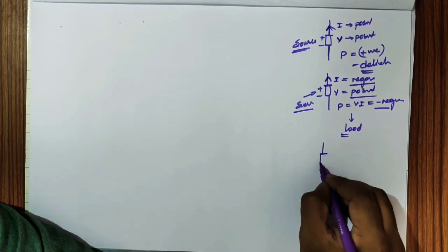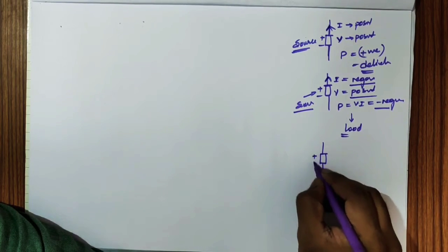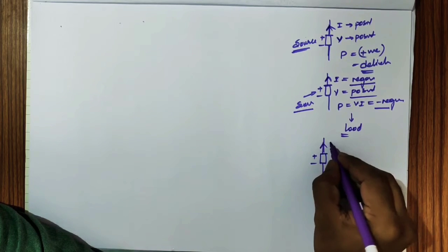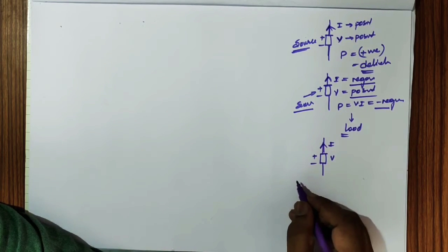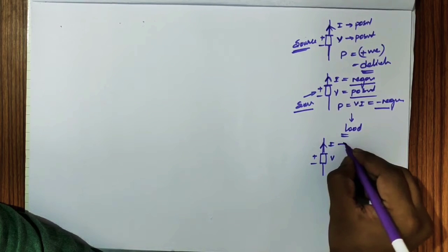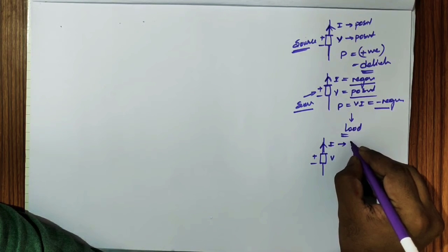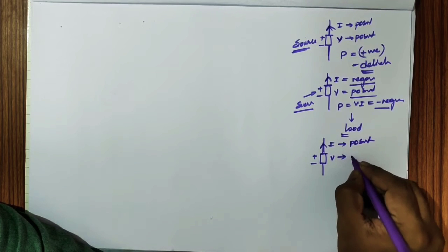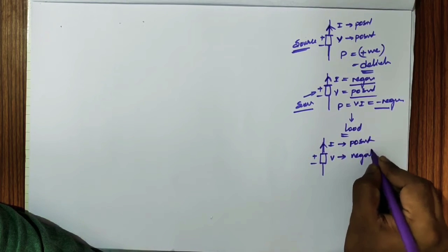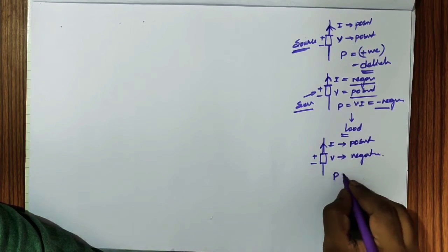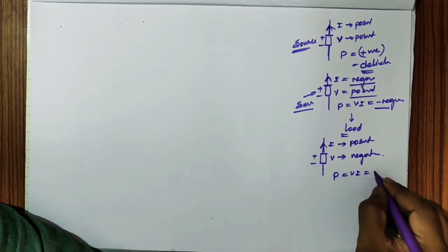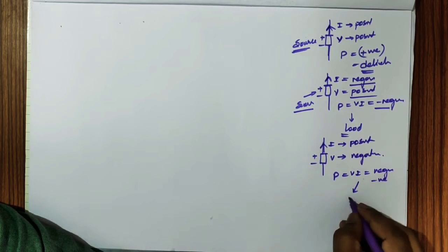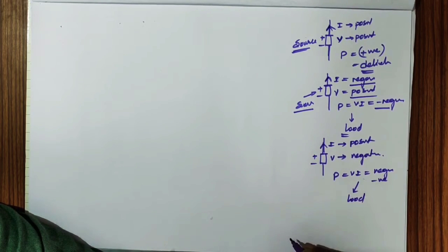Again, another case: I take this positive-negative terminal, and again the current is leaving. If the current is positive and the voltage obtained is negative, the power will be VI, which is negative, so in this case also it acts as a load.